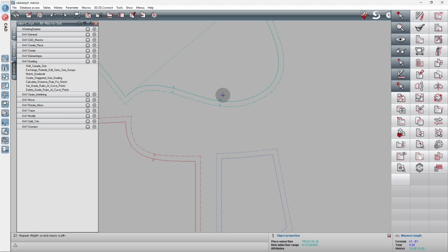In the second example, the missing rule for a notch will be calculated by selecting a sub-area between the start or the end of an element and a notch. When selecting a sub-area, instead of using the right mouse button, click left and select the section by clicking the element and the notch in clockwise order. A section between two notches could also be selected.